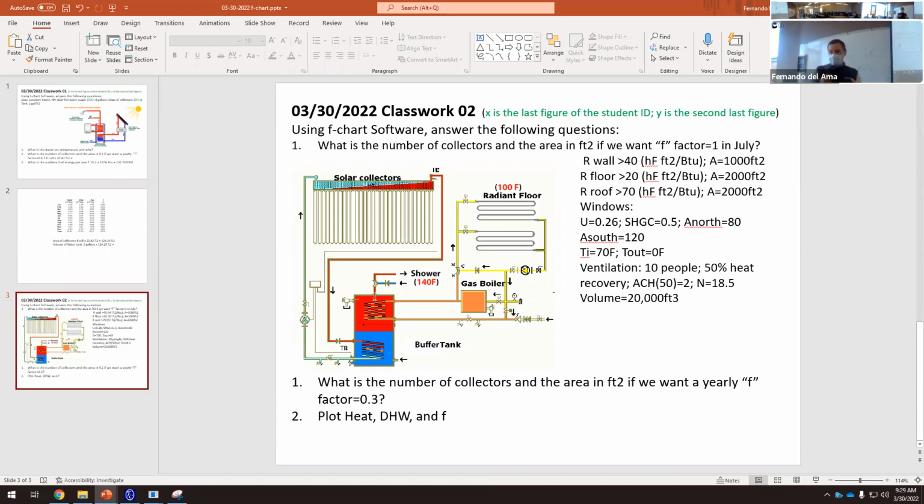In the event that they have to take a shower at noon, okay, the gas boiler can start working, but that will happen only maybe 1 or 2 days a year or a month. So knowing habits is important, because we can have the gas boiler heat up the water tank only for 2 hours, and then the rest of the time, we only need 100 Fahrenheit as a temperature. Okay, so those are the kind of things that we need to know.